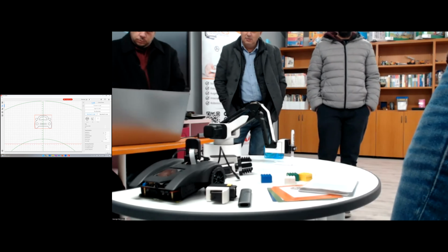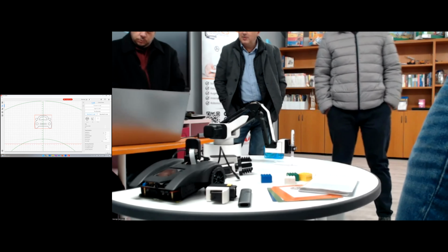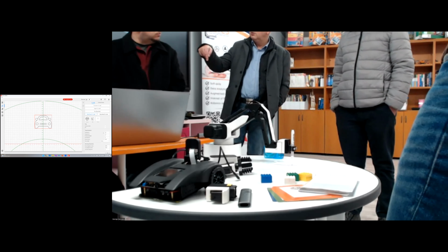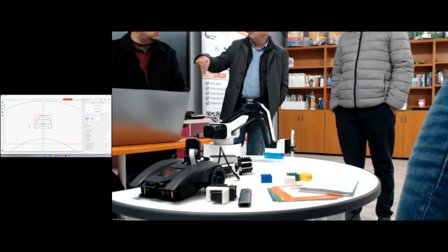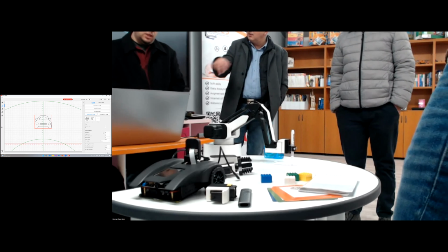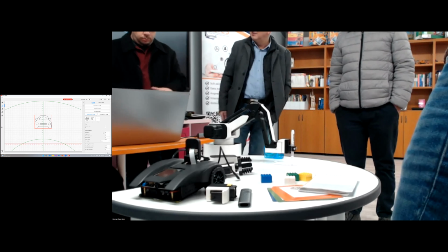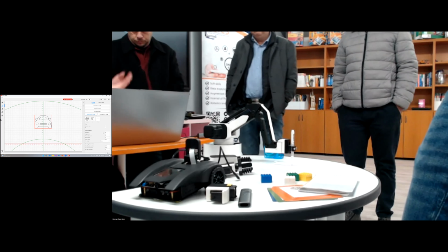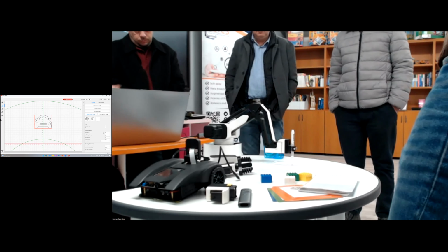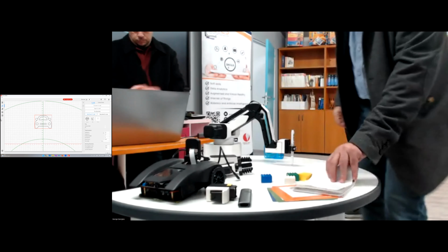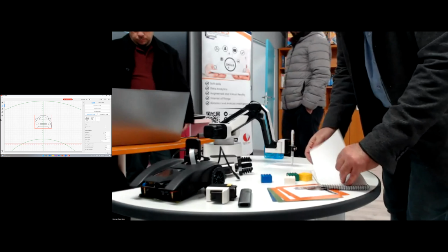I don't really know what the jog speed is. For the laser as well, if you move slow, then it cuts more. If you move fast, it doesn't cut, so you should find the optimal. And depending on the shape you're gonna do, when it's round, it's easier, of course, if you have less speed, and if it's a straight line, you can do it fast.